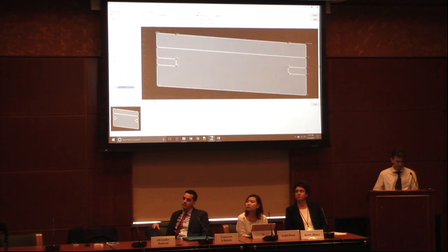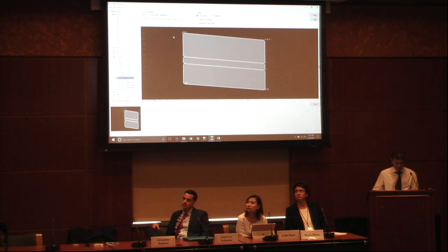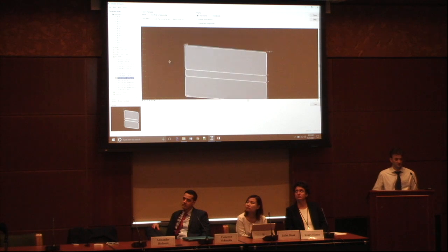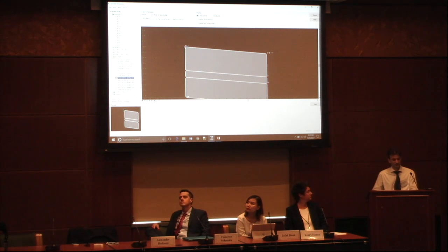So let's see, pavement, where is it? Pavement, main line. So each one of these little red crosses represents different points. Every template has a ref point here and a width point there. I connect the ref point to a width point via the interface known as a point control, which is a drop down in the program. And that width point connects to another ref, which connects to another width, connect another ref. So then that's how they daisy chain together.